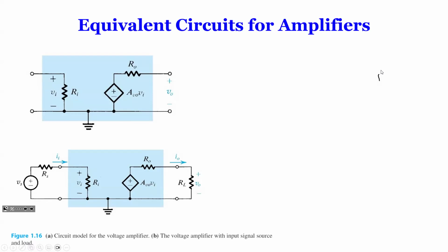So now you can analyze this circuit. This RS is usually called the source resistance. It's the resistance of a source. So in the future, if you get any voltage source, like a sensor, a pressure sensor, or whatever, and you say, oh, I got a voltage I need to amplify, that source coming in has an internal resistance. That's called a source resistance or internal resistance. Now, these two are in series, so we also call them a voltage divider.